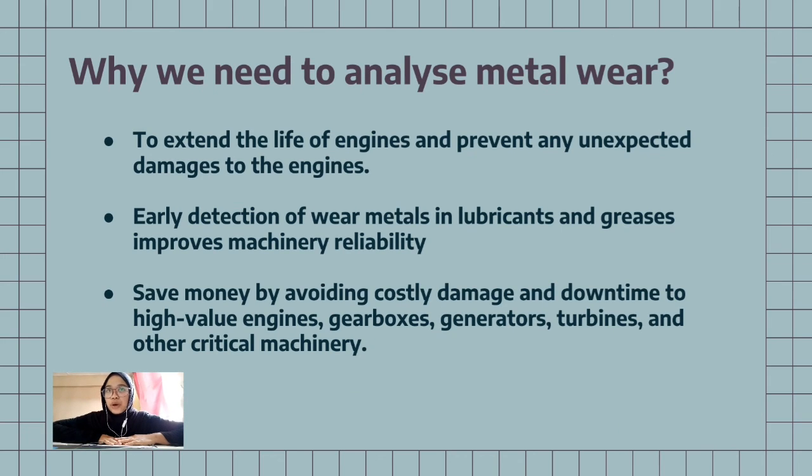The last one is why we need to analyze metal wear. So metal wear analysis helps us to extend the life of the engine and prevent any unexpected damage to the engines. Next, early detection of wear metals in lubricants and grease improves machinery reliability. And the last one is it will save money by avoiding costly damage and downtime to high-value engines, gearboxes, generators, turbines, and other critical machinery.